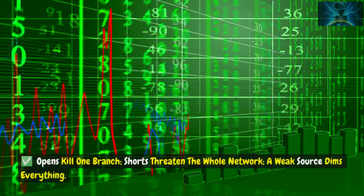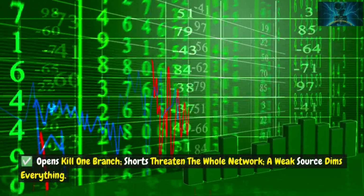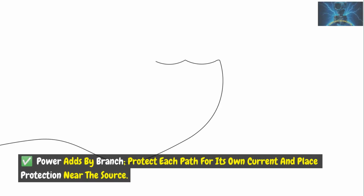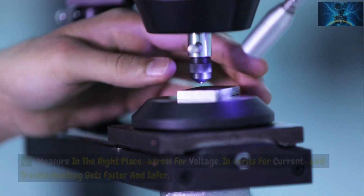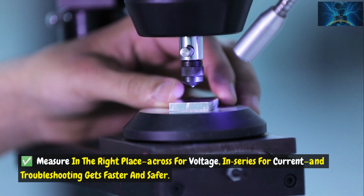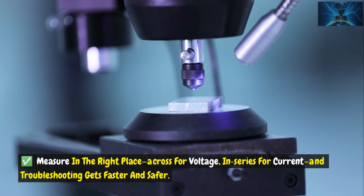Recap: Opens kill one branch. Shorts threaten the whole network. A weak source dims everything. Power adds by branch. Protect each path for its own current and place protection near the source. Measure in the right place. Across for voltage, in series for current. And troubleshooting gets faster and safer.